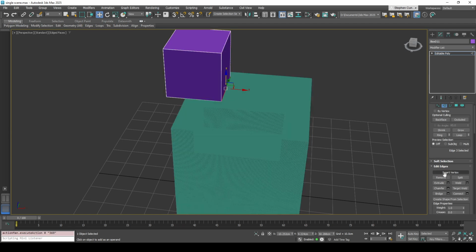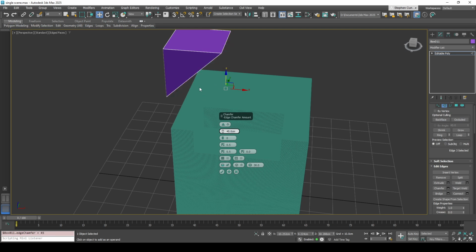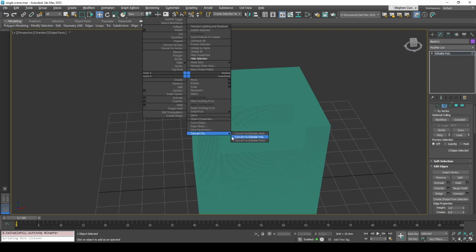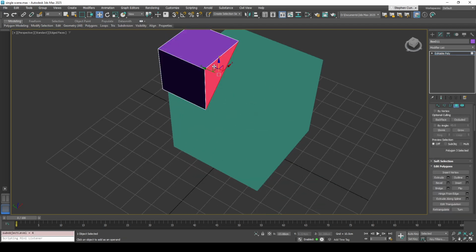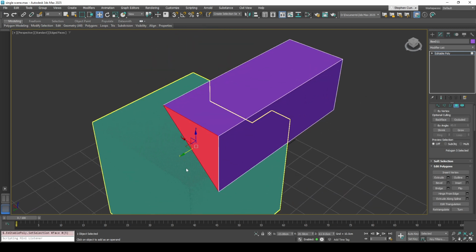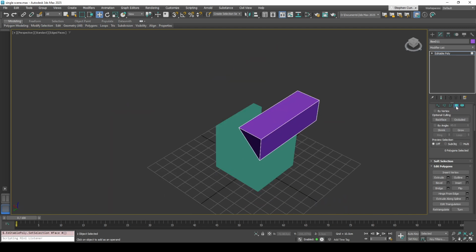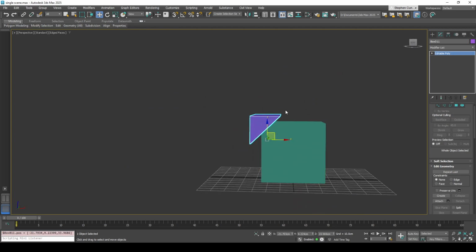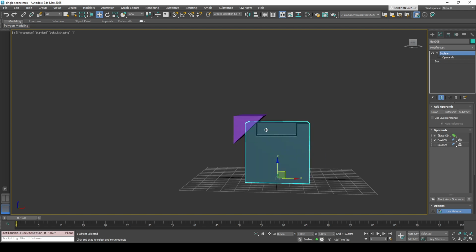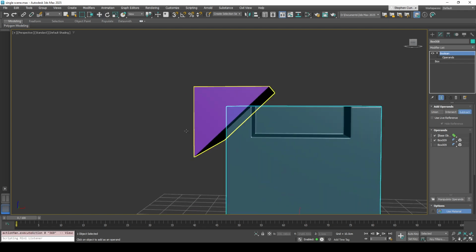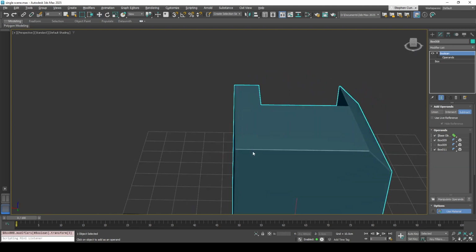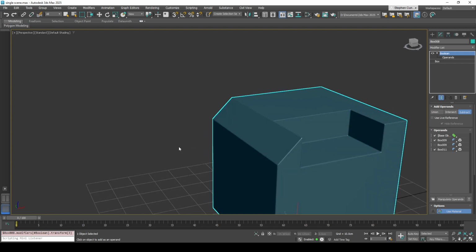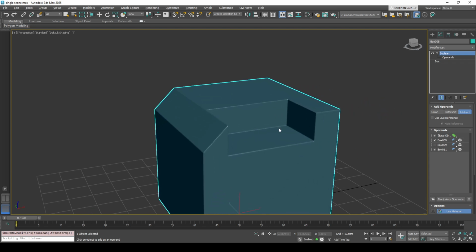You can just grab these. Let's put a chamfer on. Oops, I keep that there. Let's do, should be like 45. Got a tool now created. Just drop that down. Let's grab this. And then again, all you need to do is move it into that position, sort of here, maybe. And then we could just use the subtract. So if we lower that, subtract, grab it, and there you go. You've got that nice sharp angle that you're probably going for a little bit more in the hard surface kind of stuff.